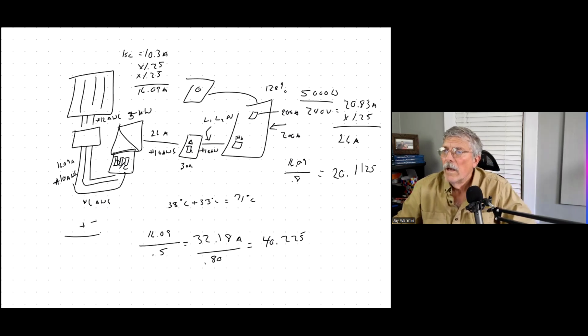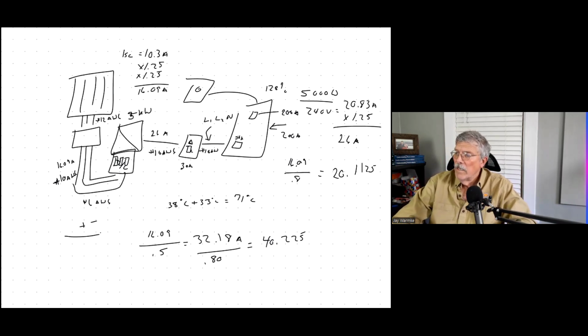Now there's also another drawing that they'll usually refer to as a 3-line drawing, and those are going to be more detailed. So you might have a picture here of your DC disconnect, and you might have the positive wire coming in here and connecting, and the negative wire coming in here and connecting, and an equipment ground wire coming into this bus bar.